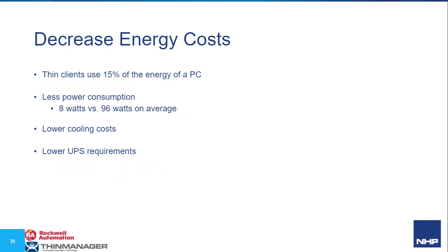Energy. We all want to reduce our carbon footprint. ThinManager does enable that. I use an example of a control room with 20 PCs at 100 watts each. So you've got 2 kilowatts of power, 2 kilowatts of cooling, 2 kilowatts of UPS. You could replace that control room using thin client devices and have a much more versatile, flexible configuration using 10 to 15% of the energy.